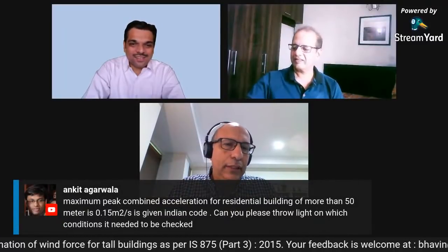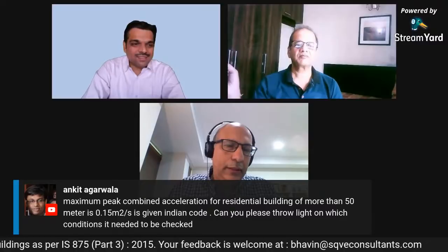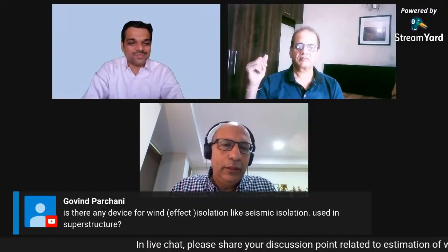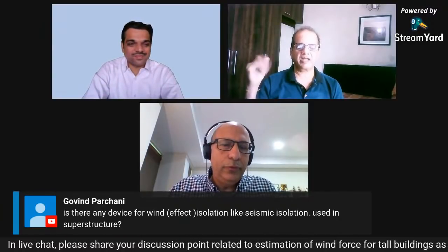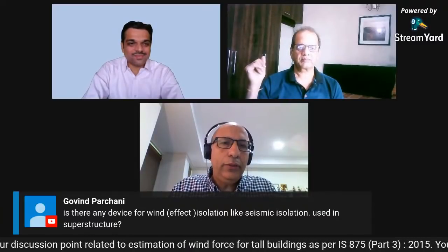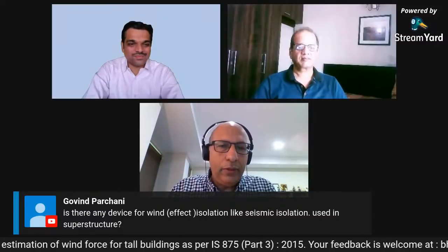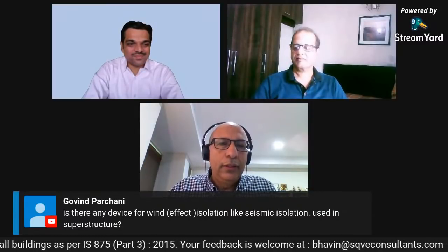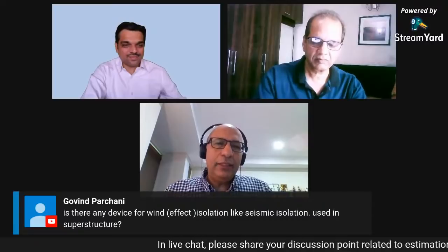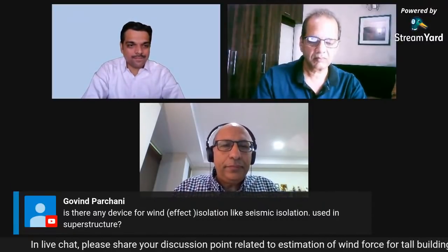And by the way, often the advantage with the liquid sloshing tanks is they are often needed anyway. So you're not adding to the cost at all for the building, because usually there's a need to have a water storage at the top of the building for fire hydrants. So the chance of a fire breaking out at the same time as a strong wind is almost zero. So you can be confident that this is a very viable approach, very low cost when you think that you need to have a tank there anyway, but we just have to shape the tank in a particular way to work for you.